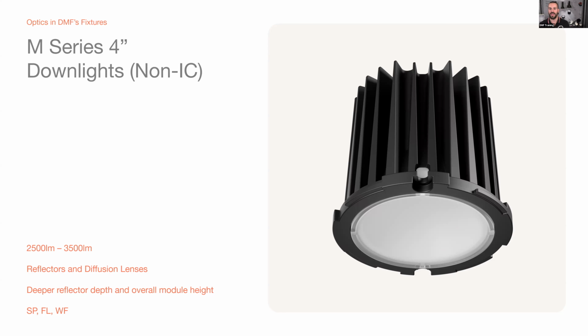One thing that shifted us to this approach is that these high lumen downlights of 2500 plus lumens get significantly hotter at the LED. They create more heat. They also rely on a larger LES, or light emitting surface. So you can see on the inside, it's a pretty sizable COB chip because we're moving up to that high lumen output. Overall, to get to a manageable beam spread, we need a deeper depth to get the geometry of the trim and the reflector to reach a spot, flood, or wide flood beam spread. So that's the combination that we have here.